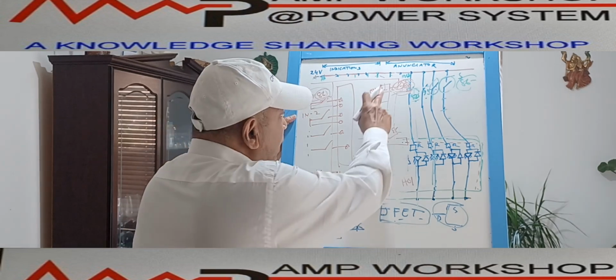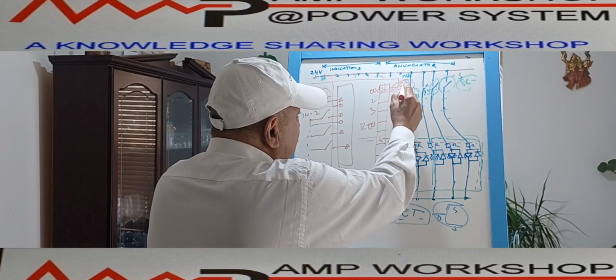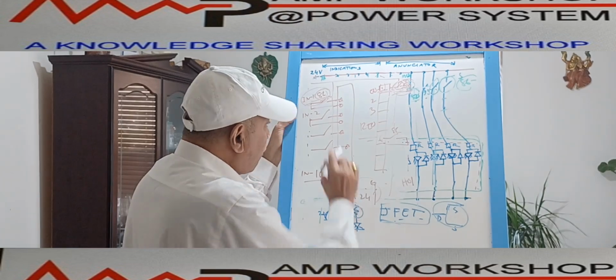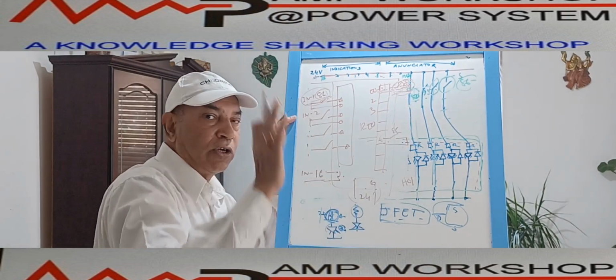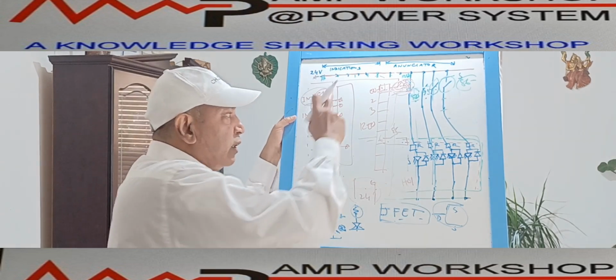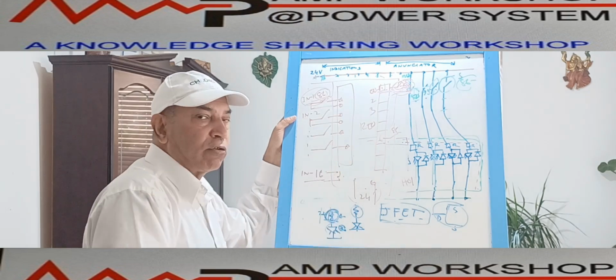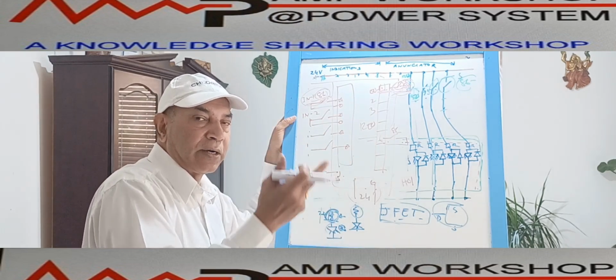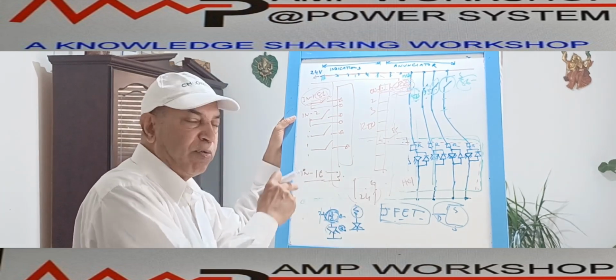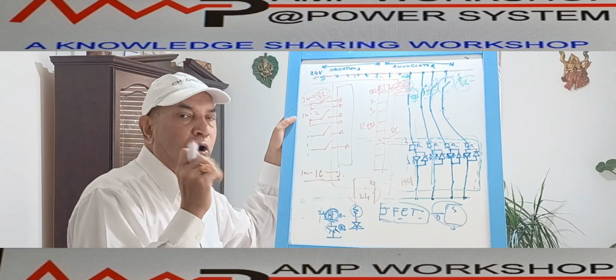The horn will be activated immediately. Suppose this relay has 2 contacts: one contact goes to the indication, another contact goes to the horn. From all outputs, one contact goes to the horn; that is internally soldered on the PCB. So this output contact commonly goes to the horn, and the horn will be activated immediately. The horn circuit is disconnected by a push button. So the moment I press the push button, the horn stops immediately.